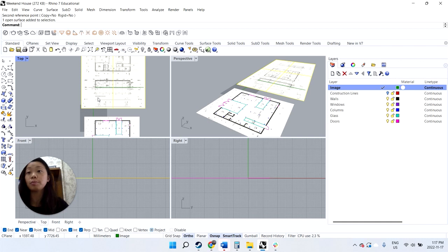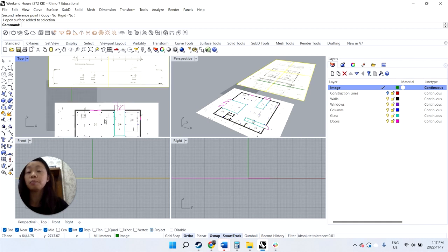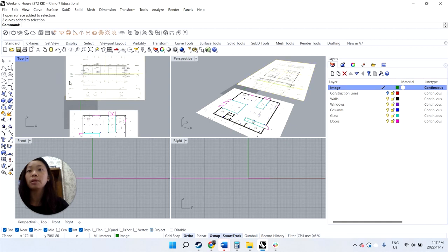In the previous video, we scaled the plan to be accurate to a known dimension. So that's how you can kind of set up 3D modeling a drawing that already exists and then getting it fairly dimensionally accurate. Again, it's not perfect because we are tracing. If you actually knew the numerical numbers, then best to go by that, but this should do for our purposes. So I'm just going to select the lines and then delete them. Those are just to roughly scale the drawing. So that's good.